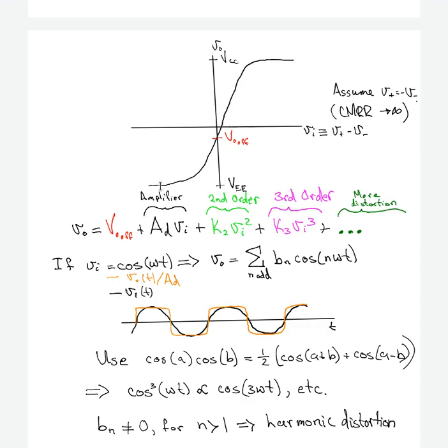It would put out this voltage. So that tends to clip off the peaks of the cosine wave on the output, making it look more like a square wave. Here we have a picture of that in time. Black is the input voltage, and the orange is the output voltage divided by A_D, so we could write them on the same scale here.